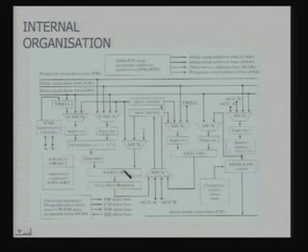This adder is distinct from that of your ALU. And the other operand for the adder can come from any of the accumulators. These accumulators, accumulator A and accumulator B, there are two accumulators, and then the output of the adder passes through the 0 detect or saturation or rounding block.